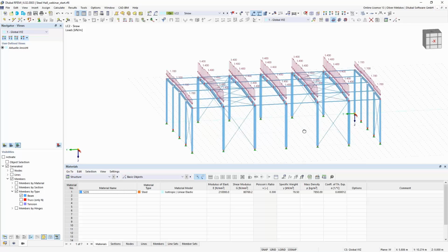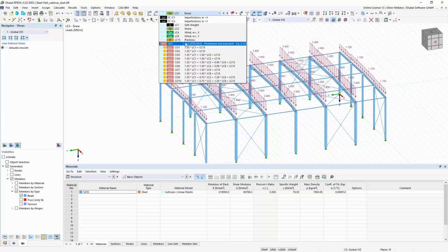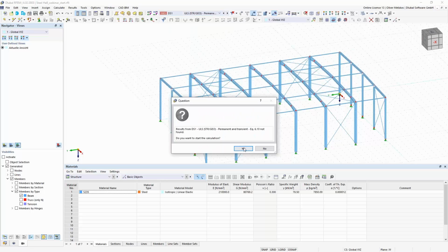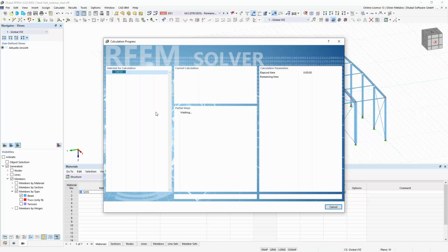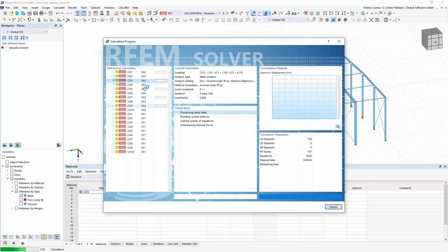Okay, so now I have changed those two settings, and I want to run now the stability analysis. I think we still have it activated from the example before. So if I calculate my design situation number 1, I have my 10 load combinations, static analysis, and then stability analysis. And now I would expect to also get this lateral torsional buckling shapes.